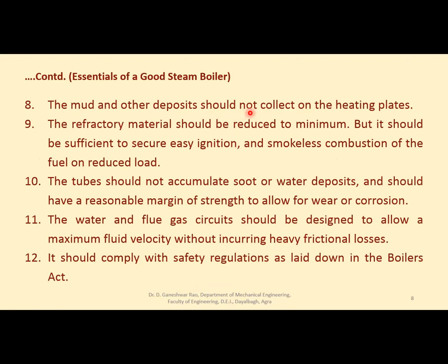Mud and other deposits should not collect on the heating plates. If mud is deposited on the heating plates, there will be less heat transfer. So heat transfer is affected, which means water will get less heat. If water gets less heat, its conversion from water to steam will be affected. So there should not be any deposits.